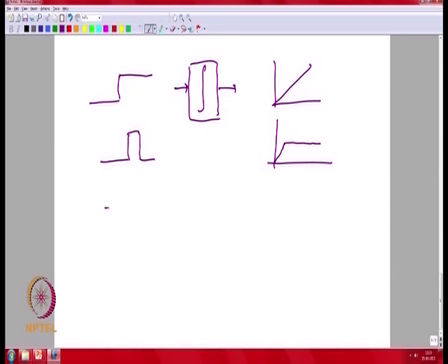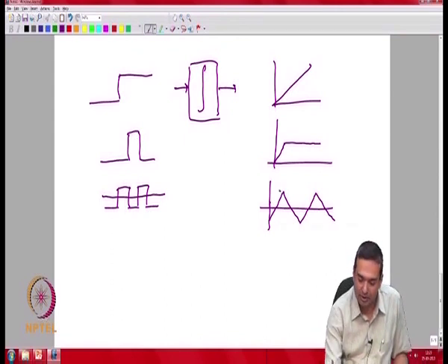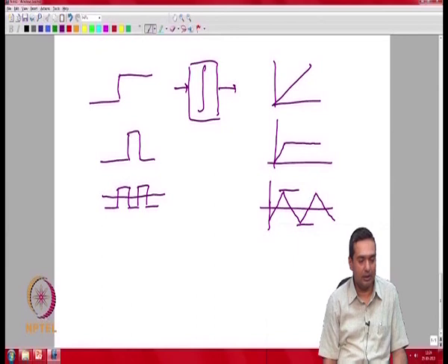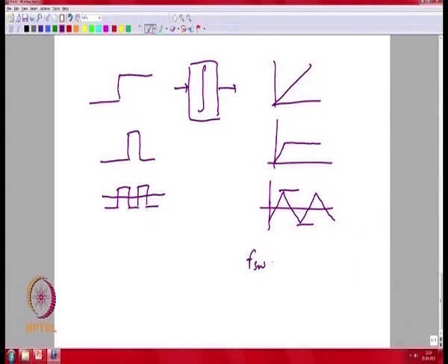If you have something which is having a pulsed input with an average of 0, essentially what you would have is, in this particular case, the output of such a waveform would be, the integral of that would be a ripple. The ripple would be riding on top of whatever is the fundamental that you are trying to apply to the load, and the magnitude of the ripple can be reduced by selecting a larger inductor or a larger capacitor for improved filtering. So, many physical processes naturally have integrators in them, and they lend themselves to PWM action, and the constraint is that your switching frequency is assumed to be a lot larger than your maximum pole frequency of your plant.